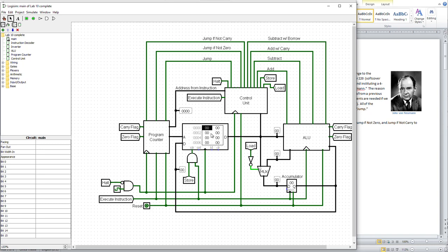to look in, which means 8 bits, or 256 unique addresses, isn't going to be enough. We need 16 bits for 64K worth of addresses. So we're going to need two cycles just to get the memory address to go to. And then the last one is going to be to actually execute that instruction. That four-step execution cycle is known as the von Neumann bottleneck because now it's going to take 4 times longer, 4 times more clock cycles to execute a single instruction.